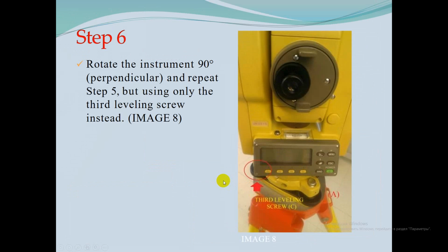Next step, step 6. Rotate the instrument 90 degrees to perpendicular and repeat step 5 with the third leveling screw.